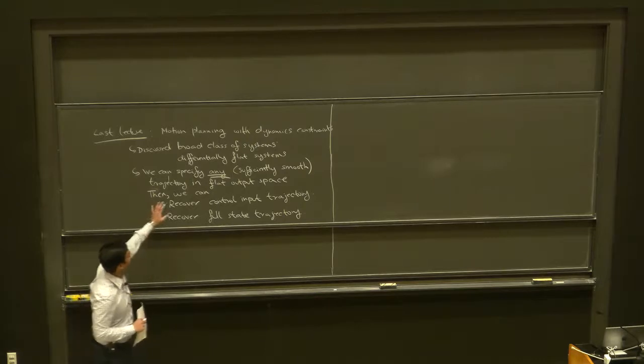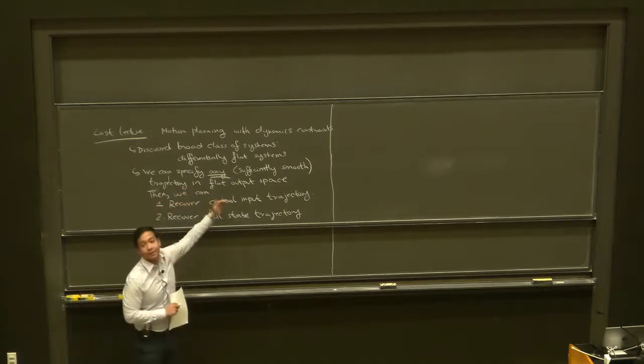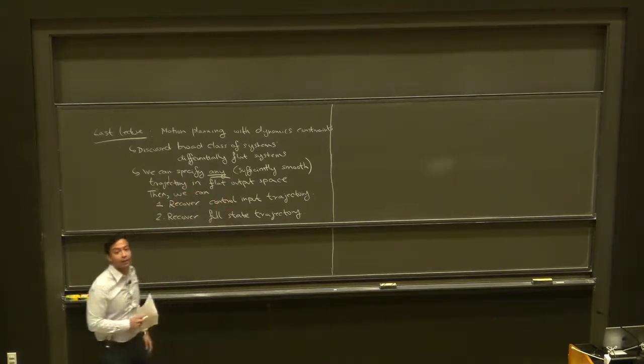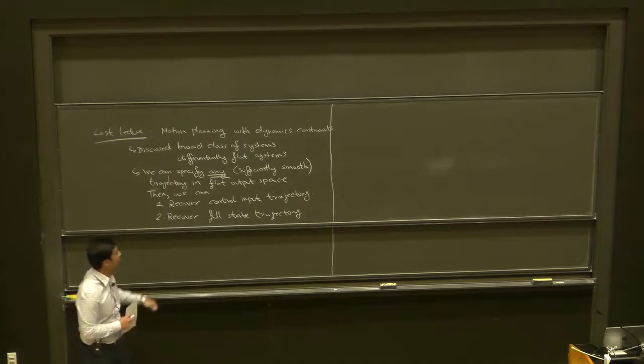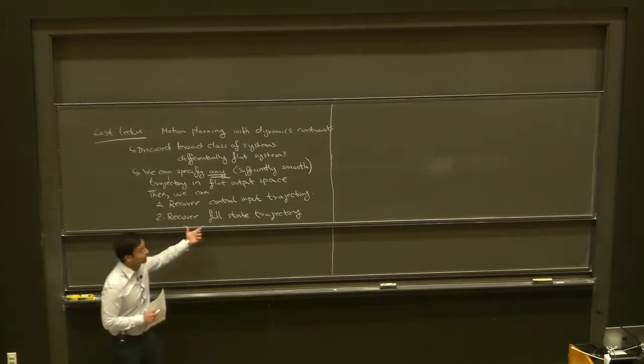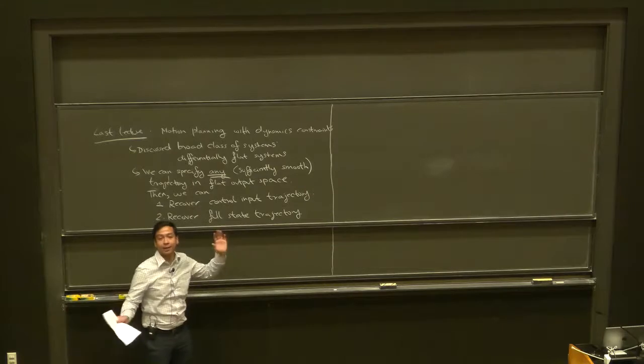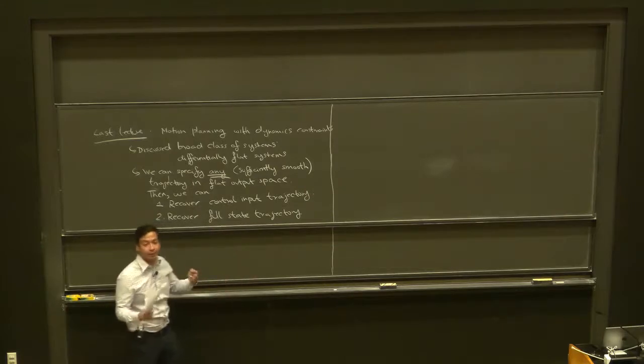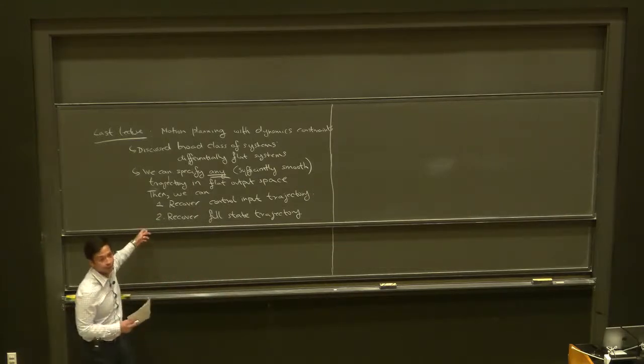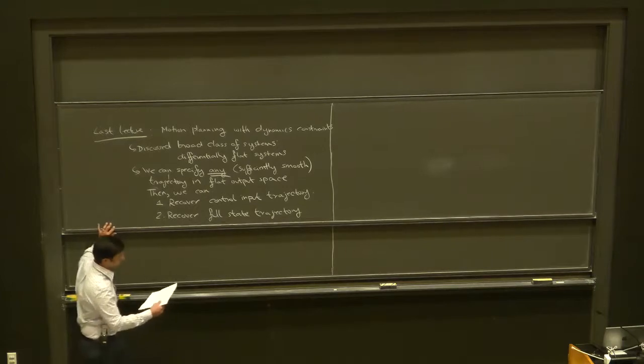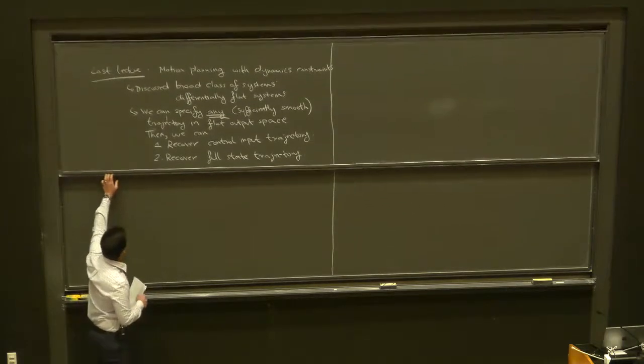If you come with a center of mass trajectory, I can get the system to follow it. The other states might do something wacky or weird. We don't have direct control over them, but we can directly control the center of mass. That's what differential flatness gives us.